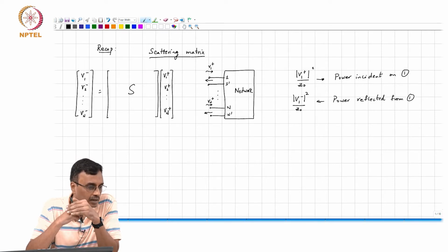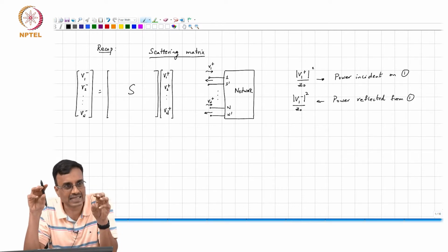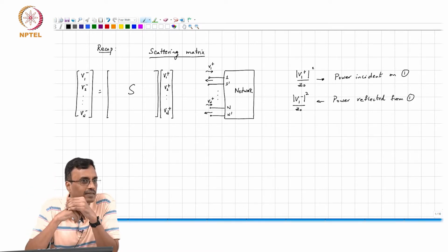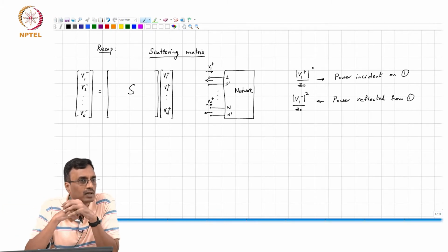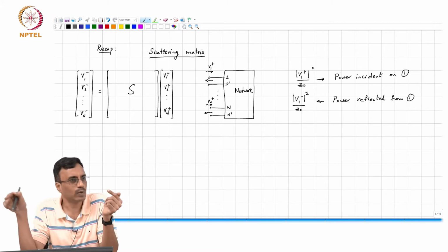So the long and short of it is that if the terminating impedance is not exactly the same as that of the line, the impedance will be a function of the length of the line as well as the frequency.